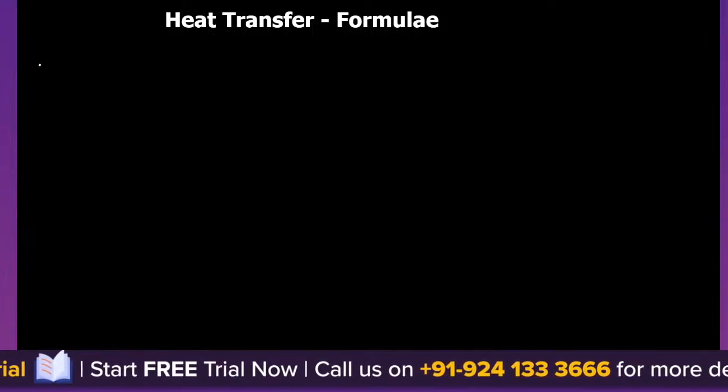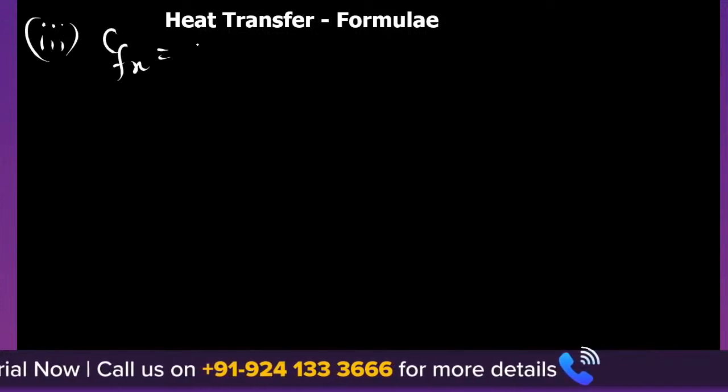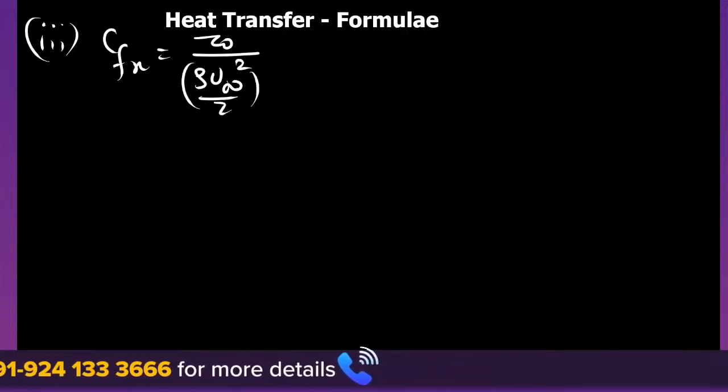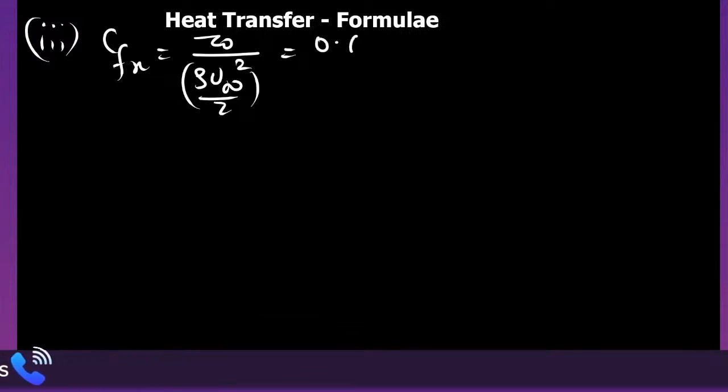Now another formula is the local drag coefficient, that is tau naught upon rho u infinity square by 2. It is given by 0.664 upon under root of Rex.